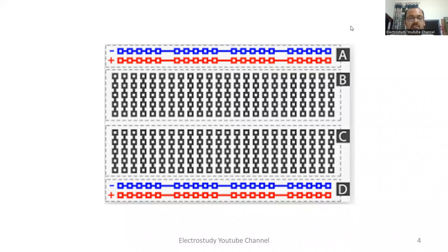I would like to add one more point. Please observe the diagram very carefully. This is a cross-sectional view of the breadboard. Now let us look at the center portion. See, all the lines are interconnected inside the breadboard, like this. All the connections are interconnected vertically. If you connect at any point, it will be the same. Suppose whatever I am drawing now, you can see very clearly. Wherever I connect it, all will be under connection only. Understanding now? So in this center portion, all vertical lines are connected to each other.